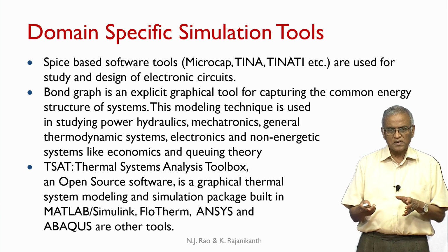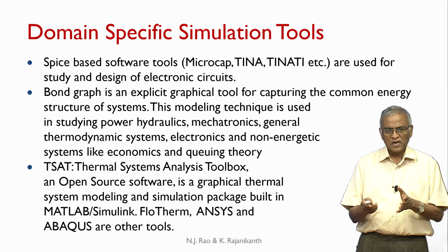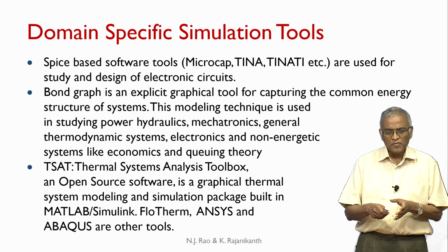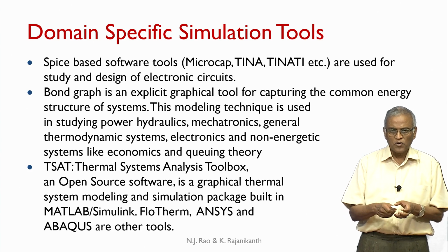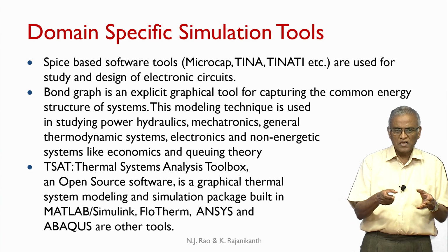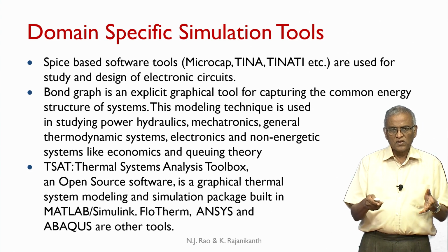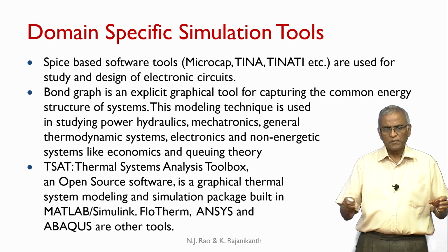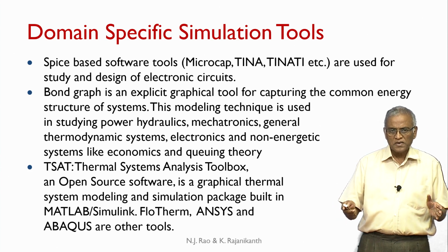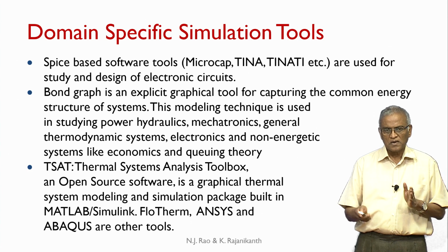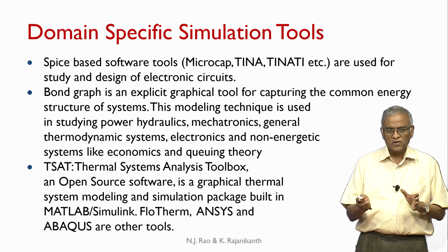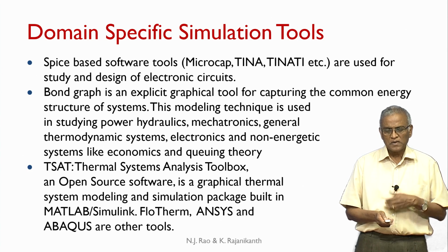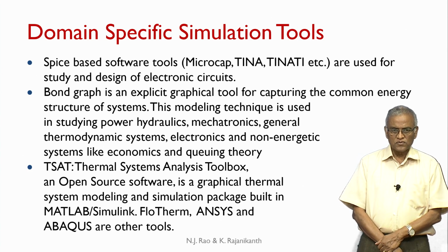Your electronic circuits respond in microseconds, sometimes in nanoseconds, whereas mechanical elements will take a few milliseconds or more, possibly a second also. So, when you simulate behavior over such widely varying time scales, you need to be careful about your modeling and the way you want to handle and predict systems. For that kind of thing, bond graphs seem to be a very effective tool.